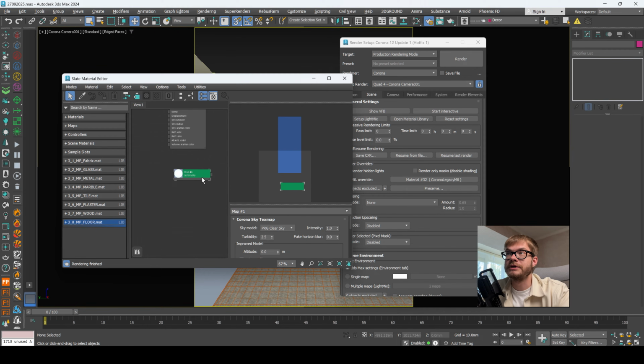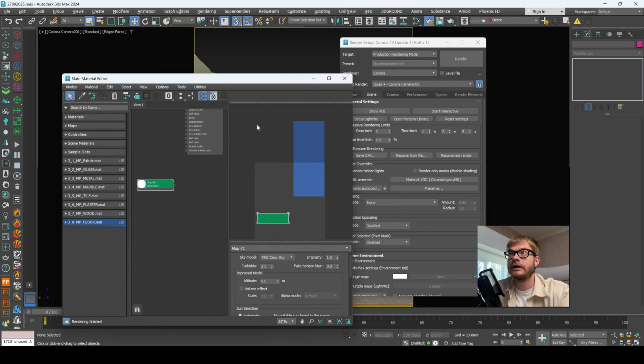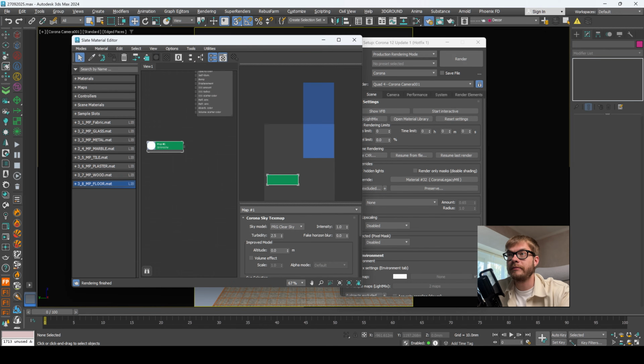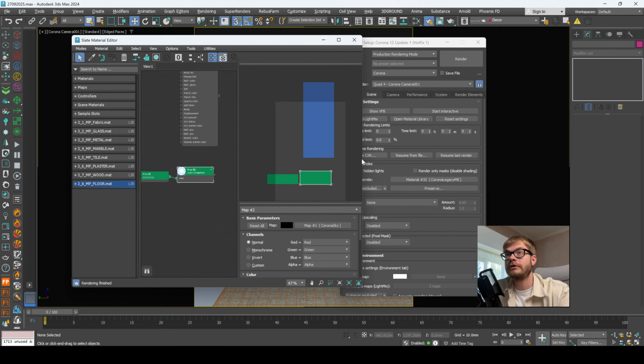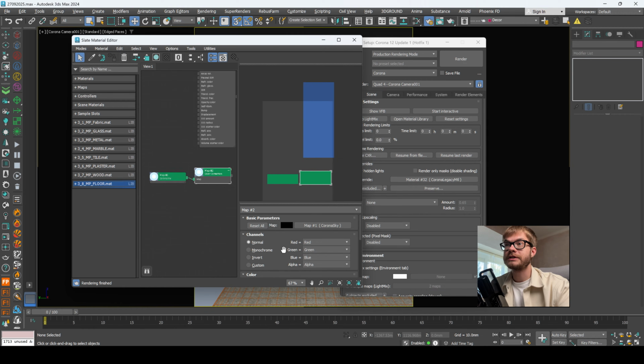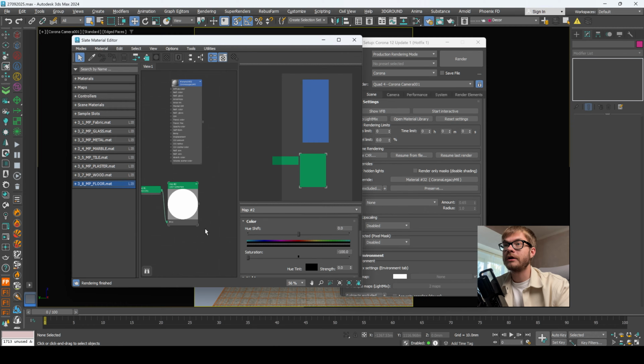This is going to be our ambient scene light. Right now we have to set up our ambient light. So create Corona sky. Here I would like to set up my Corona sky map. Usually I use turbidity at 1.7 and create map general color correction. To set up our light in the scene, select color correction and indicate saturation at -100. In this case, our sky will be gray colored.